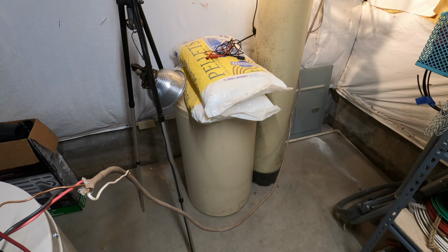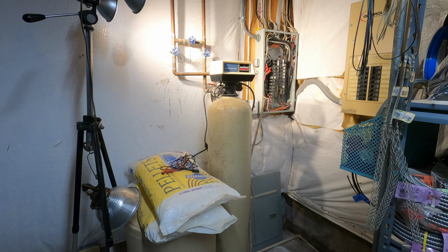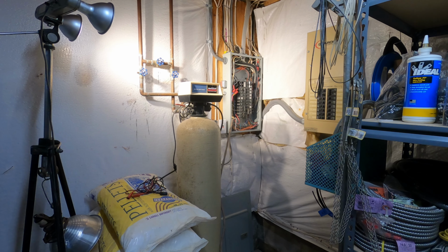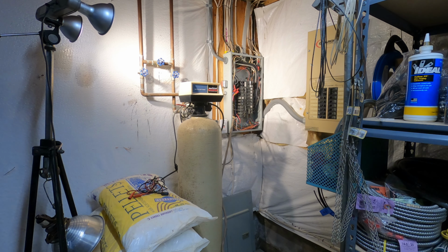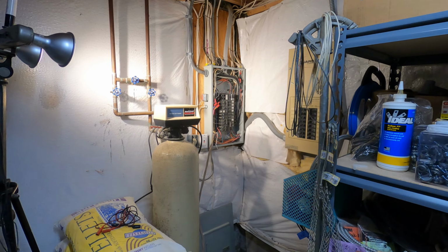I've connected temporary power with a 10-foot length of NM cable to a circuit breaker in my main panel. It's 10-3 with a ground, and only the black and red conductors are in use, with the white wire simply bent back out of the way.